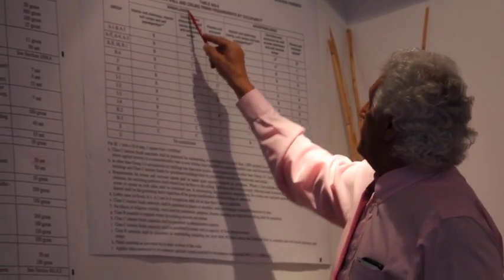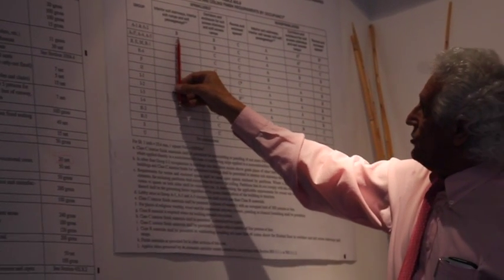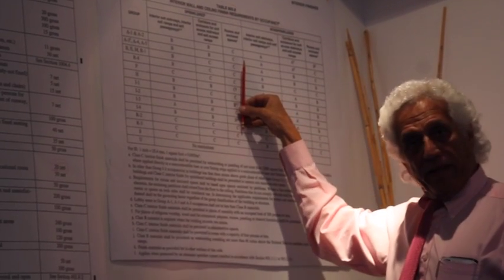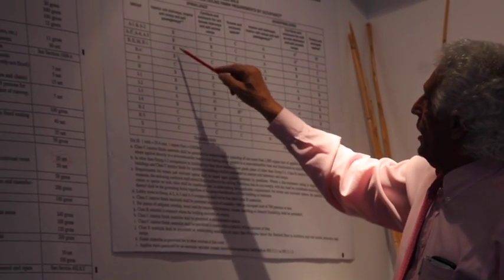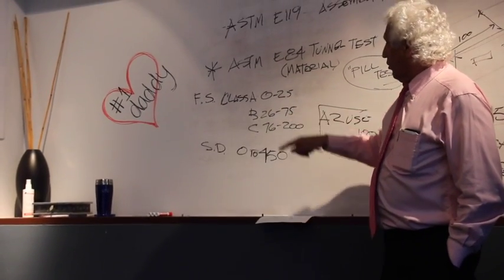We have a sprinkler building and a non-sprinkler building. You have exit stairways, corridors, and rooms and spaces. So what that does is these numbers here will tell you which of these classifications that material and that wall have to be, whether it be a class A or B or C.